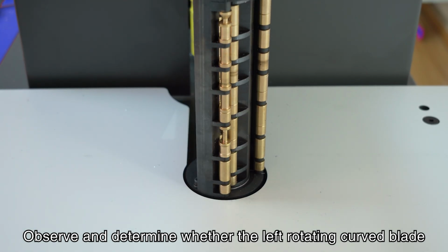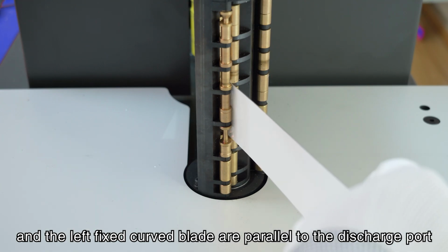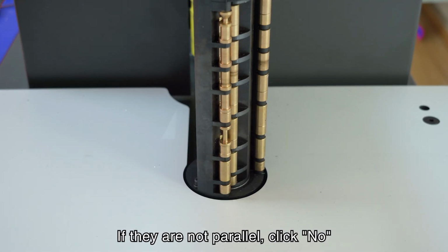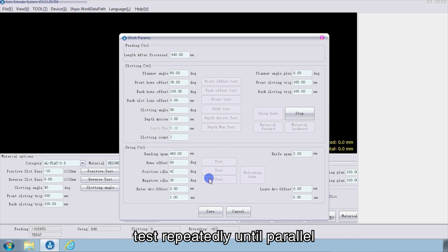Observe and determine whether the left rotating curved blade and the left fixed curved blade are parallel to the discharge port. If they are not parallel, click no. Change the negative idle parameter, test repeatedly until parallel.